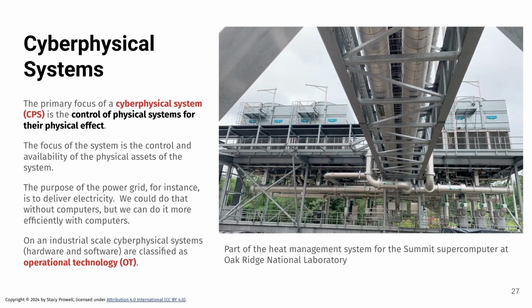If that's not sufficient, it can pump it up into these cooling towers. And if that's not sufficient, it can run the fans. If that's not sufficient, it can actually run the chillers. But it can make those decisions based on the ambient conditions and the temperature of the water coming off the system and be very much more efficient.